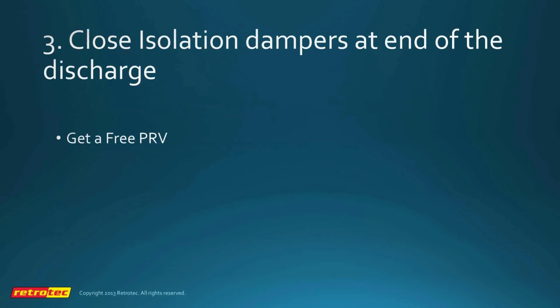An important tip would be to close isolation dampers that will be isolating the building HVAC from the enclosure at the end of the discharge instead of at the beginning of the discharge. There's very little agent loss when the dampers are closed as long as the system behind them has been deactivated.